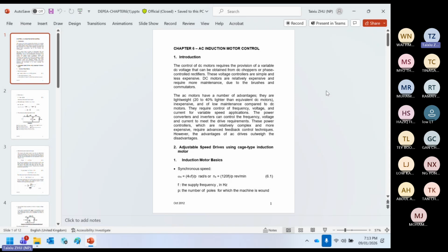But in the three-phase AC motor, you have the induction motor. The other popular one used in the electric vehicle is the permanent magnet synchronous motor. The three-phase induction motor and the permanent magnet synchronous motor are actually very similar. Sometimes the same drive can power both if the sensing components are correct, because when you drive the permanent magnet synchronous motor, you need to know the position of the magnet. But for the induction motor, there is no permanent magnet in the rotor.